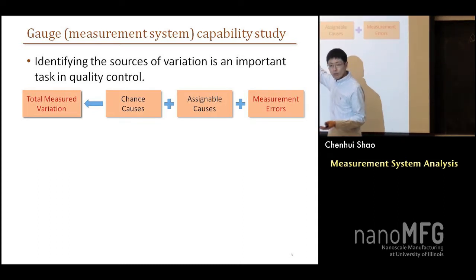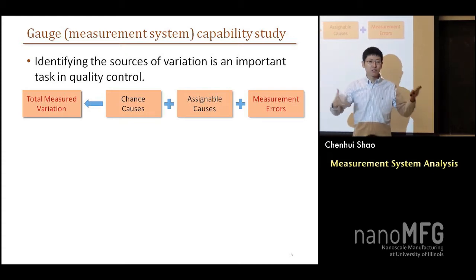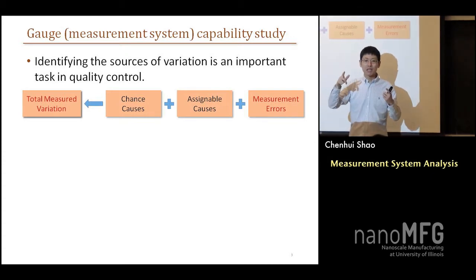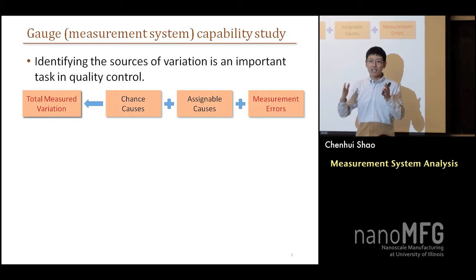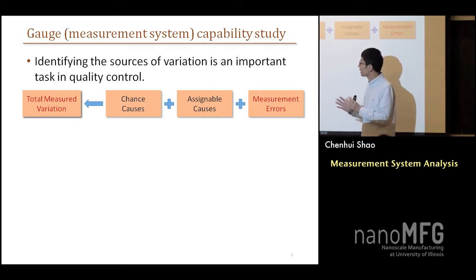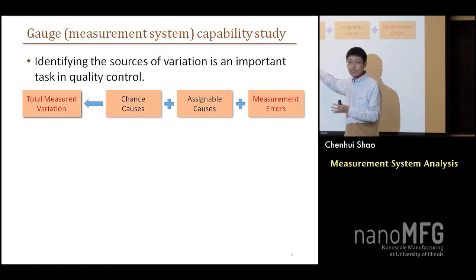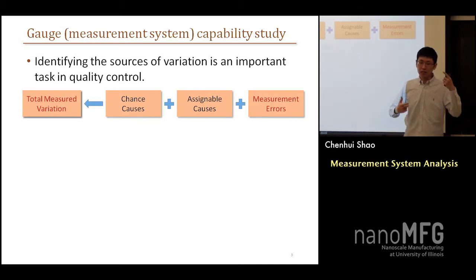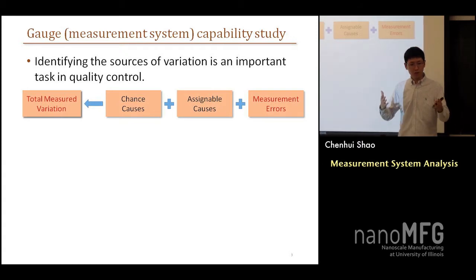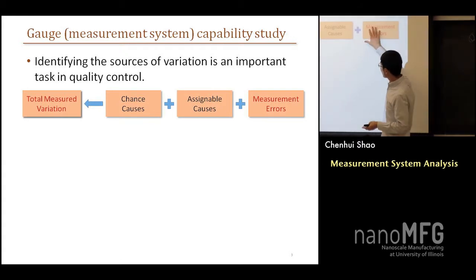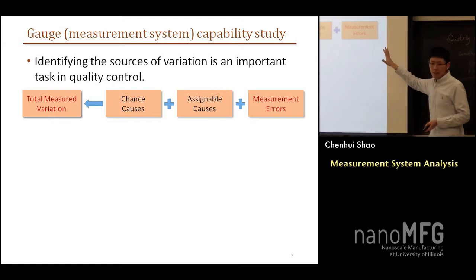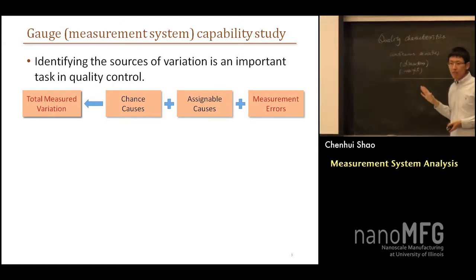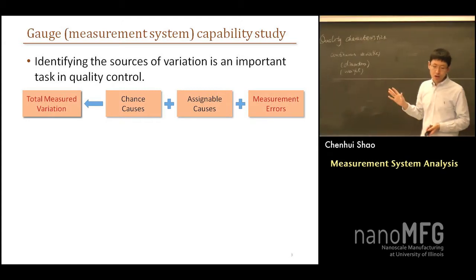For this one, we already know we can use 3 sigma or 4 sigma, whatever you want, right? You have sigma hat, you can have an R chart, X bar chart to do estimation, you can estimate your natural variation. And for this one, you can also take measurements of a number of products. You take X bar, you take R, you take S squared to do our estimation. But for this one, it really has to be estimated, but we don't know how.